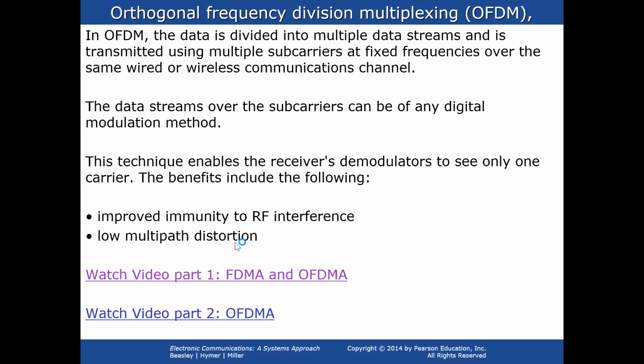There are 2 points to be noted here. Firstly, the subcarriers are overlapping in frequency domain. As we can see, the subcarriers are placed in a manner that all the other subcarriers have a zero component at the peak of one subcarrier. Such subcarriers are called orthogonal. As a result, a mobile can sample the frequency and phase without any interference from neighboring subcarriers. Orthogonality is achieved by ensuring that all the subcarriers have the same symbol duration Ts, and the subcarrier spacing is maintained at delta F equal to 1 by Ts.